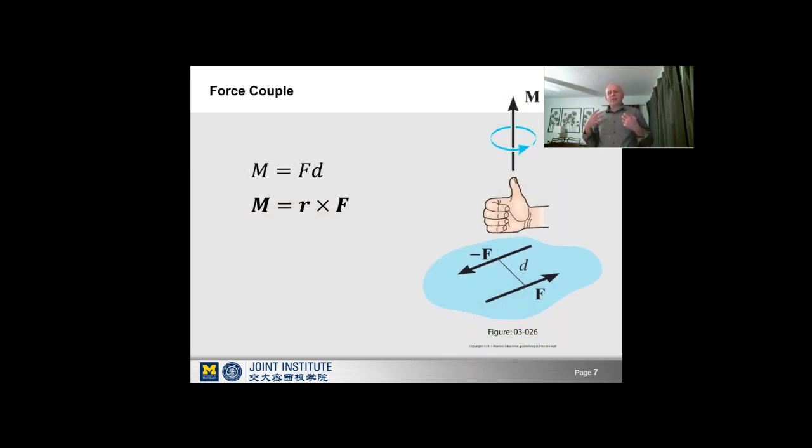But one of the easiest ways that we think about applying a moment is that we have some force couple. So if I just held onto your shoulders here and I wanted to rotate your body, I'd push this shoulder, I'd pull that shoulder, and I'd rotate your body that way. That is called a force couple because I can apply the same force on both sides, and that's just going to rotate you about your axes, right? So that's helpful for calculation. In that case, if you had a force couple in this way, you just say F times D.